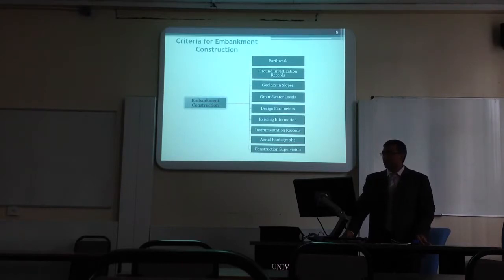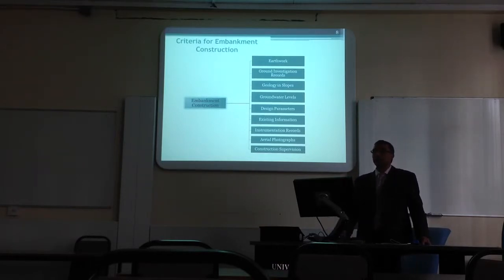The design parameters are c' and phi', which we derive from the soil condition. The existing information, of course, is important because the utilities, the telephone and electricity companies, have a lot of old data of the site, so you can get a lot of information from that. And instrumentation records like piezometer, extensometer, if there is any data.